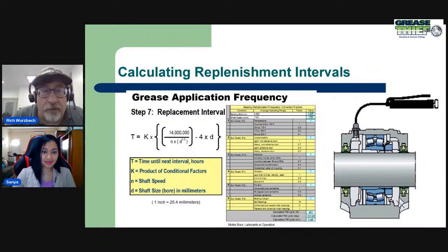There's also a factor that's related to the type of bearing. So a ball bearing is kind of the mildest damaging bearing type, if you will, to the grease, because it has a smaller profile along that raceway. But if you have, say, a tapered roller bearing or a spherical roller bearing, it's like a steamroller, and it's smashing through that grease and it's breaking it down more often. So you'll see adjustments, whether it's a ball bearing. Typically, if all your conditions are the same, it's a ball bearing versus a cylindrical roller bearing, you'll grease the cylindrical bearing more often because the grease gets beaten up, its consistency runs out. And so there's all these calculated adjustments that we can make.